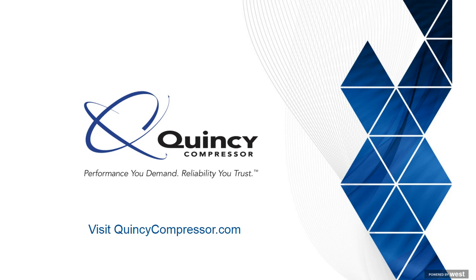If you're getting a quotation or you're looking at technical data, it's good to ask if this is ISO 1217 or according to the new DOE test standard, and it's good to be comparing apples to apples because there is a difference in the accuracy requirements and there's a difference in the published values. And once you have two different entities both publishing to the standard with isentropic efficiency, it's very easy for a consumer to compare the efficiency of two different compressors at the same pressure.